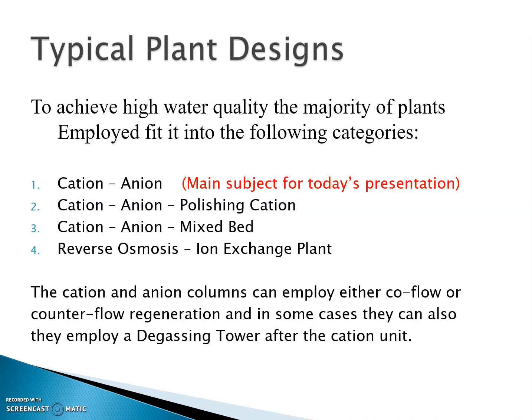In this process, strong acid cation resins in the hydrogen form convert dissolved salts into their corresponding acids, and strong base anion resin in the hydroxide form removes these acids. Demineralization produces water similar in quality to distillation at a lower cost for most fresh waters. What are the actual principles of demineralization? A demineralizer system consists of one or more ion exchange resin columns which include a strong acid cation unit and a strong base anion unit. The cation exchange resin exchanges hydrogen for the raw water cations, and the anion exchange resin removes the remaining ions from the system.